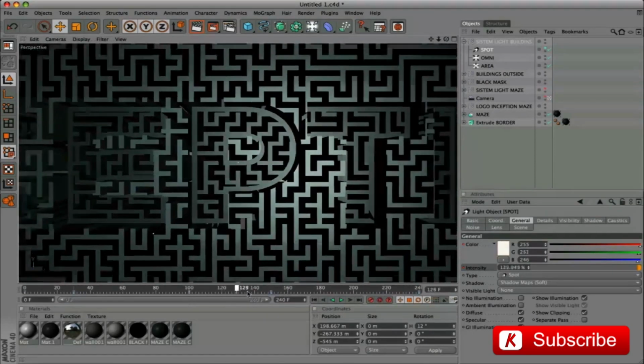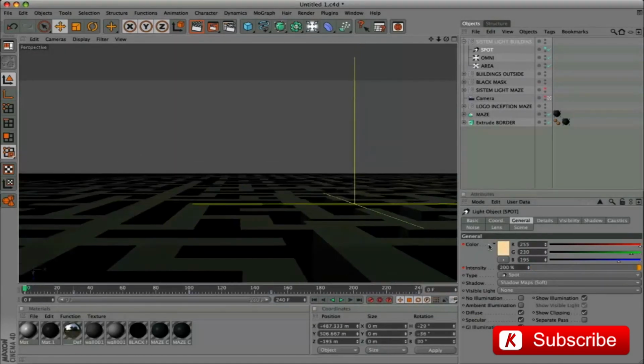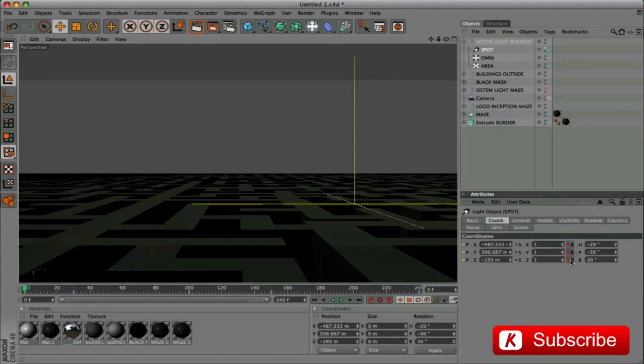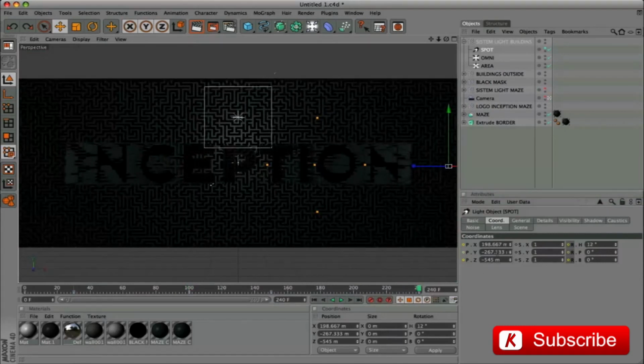The 240 frame is okay. In the coordinates panel, delete animation keyframe. Insert value x -1377, y 274, z -517, rotation -81, -22, -8.